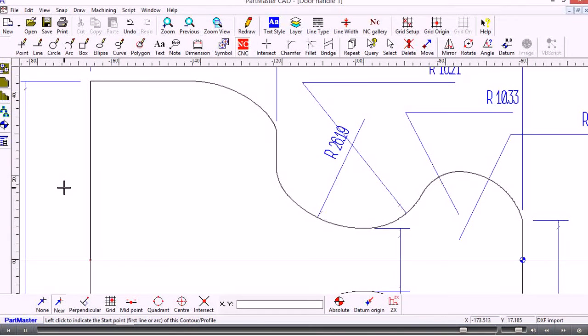One other thing is to try to always get the profile finishing back at the center line. So if we start at the center line as we have done here, then you should finish at the center line there. So that will be the start and end point of your profile. We'll show you how we can machine that shape in the next video.